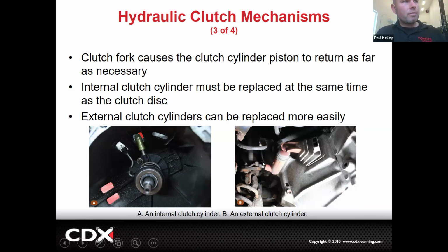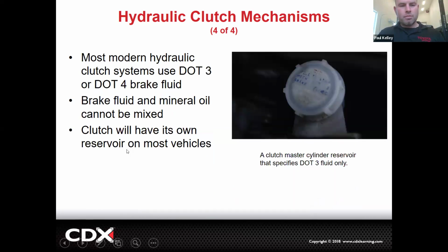Here's the bleeder for this one. Remember, this one we send the bleeder out through the bell housing. Cool. So they use DOT 3 or DOT 4. You could upgrade it to DOT 4. It's got a higher heat rating, but DOT 3 would probably be fine.